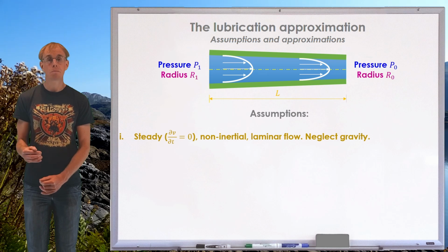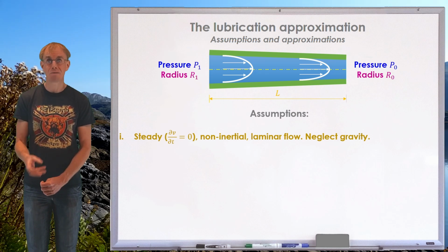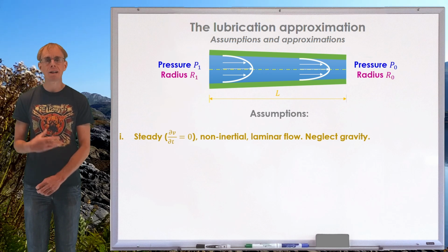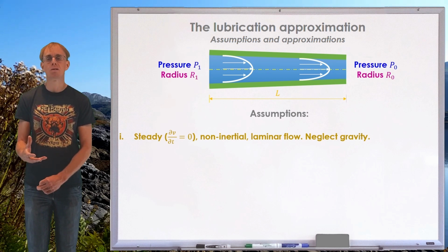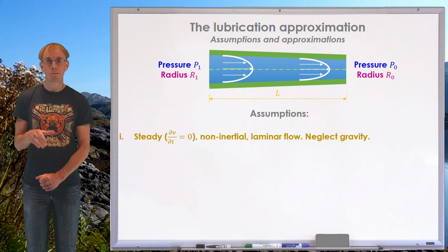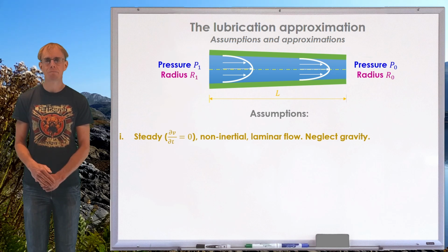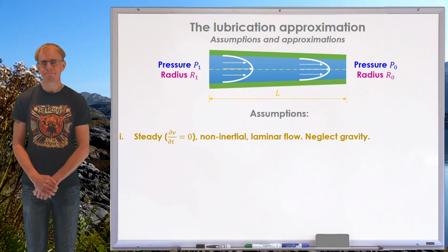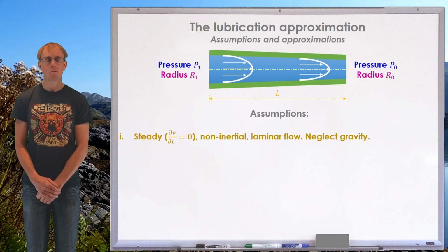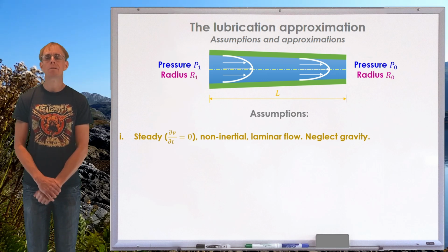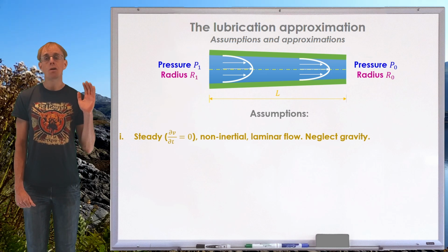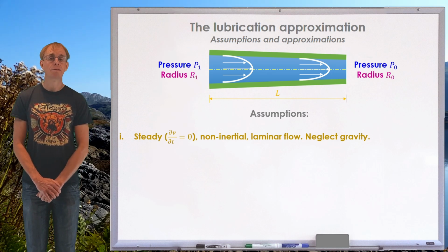This is fine in polymer processing because don't forget most molten polymers have incredibly high shear viscosity, order of thousands of Pascal seconds. And so a Reynolds number based on a 0 shear rate viscosity is likely to be very solidly in the creeping regime. So that allows us to make this assumption in safety. Since we're creeping flow, we're already laminar, so we don't have to worry about the onset of turbulence. Since this tube is horizontal, we're also going to neglect the effect of gravity.